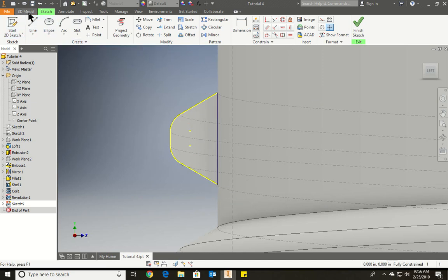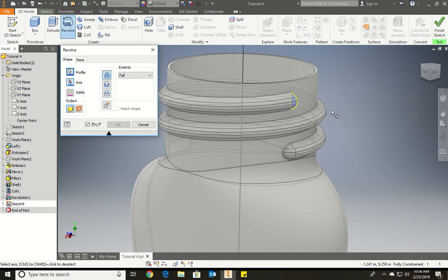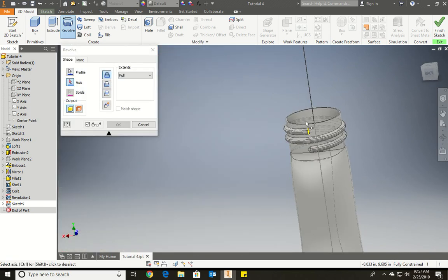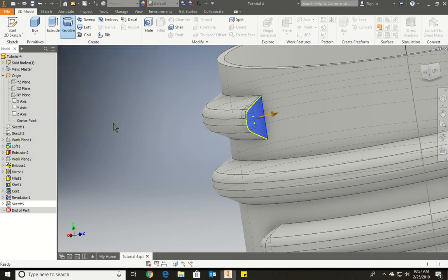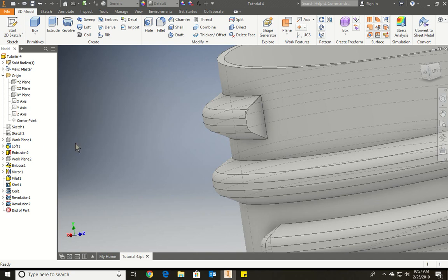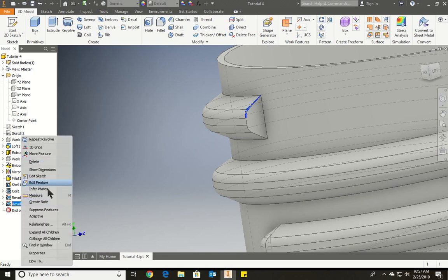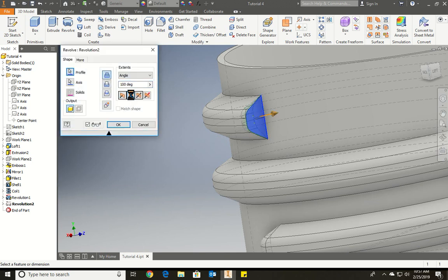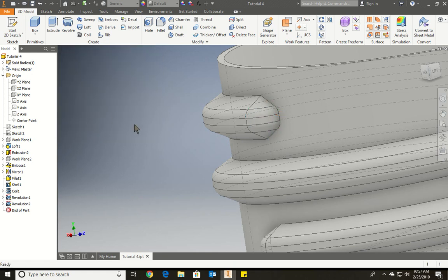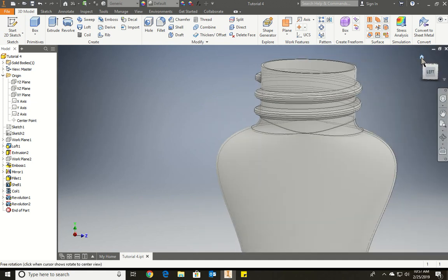Then from there we're going to use 3D Model, Revolve. It's going to hide it again for you, like so. We're going to use axis, we already have it right here. And we're going to type in angle 100, right? Press OK. No, it wasn't 100. Let's go back to this one. Edit. I think we have to flip it the other way. That way. We have to flip it the opposite direction. And 100 works as well. So it looks something like this. Okay? Press the home button.